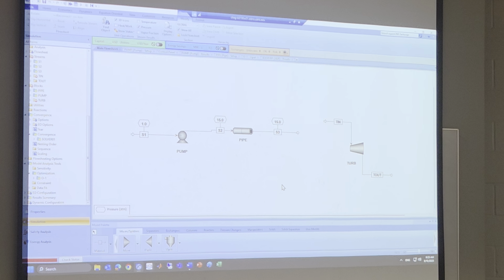Does anybody have an idea? No idea? Okay, I give you the idea. You can sectionize. Choose here, right click, change section. You can create a new section. So I sectionize the first simulation S1, the second simulation S2. For change section, create the new section S2. We are using two different property methods.